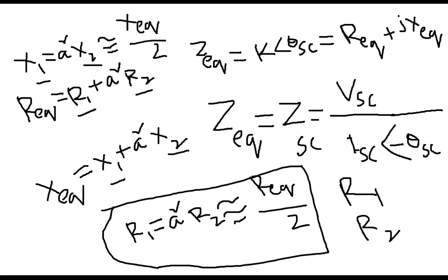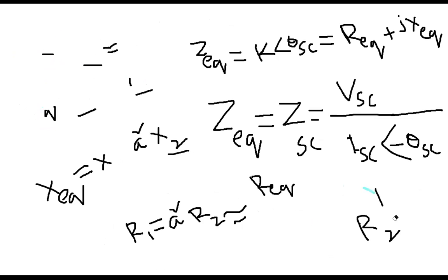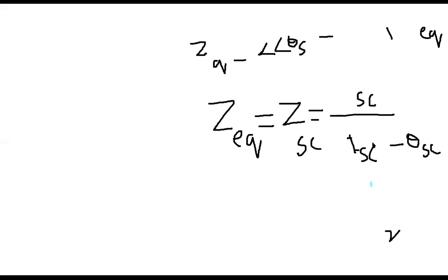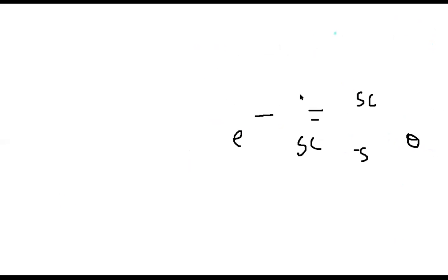And then I'm saving this one. Now I want to discuss, I already said this is fine. Now I want to discuss the open circuit test. You see, we got 4 parameters, R1, R2, X1, X2. Now 2 parameters are remaining, RC and XM, the magnetizing or the core material, those 2 parameters. So I have to conduct the open circuit test. Now I will make the open circuit test. So let me get the title.